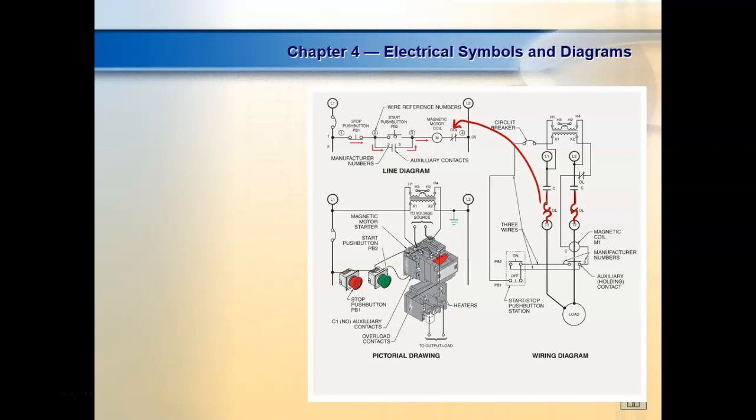So most of the time, it's like a circuit breaker in your house. Normally if you're standing at a circuit breaker, when it pops, you can't reset it, because you got to wait till it does what? Cools off a little bit. So even these are the same way. So normally you would reset it once, and if it comes up and everything's okay, you leave it alone. If you put it back down and it runs for 10 minutes and pops again, you don't tie the overload reset down, right?